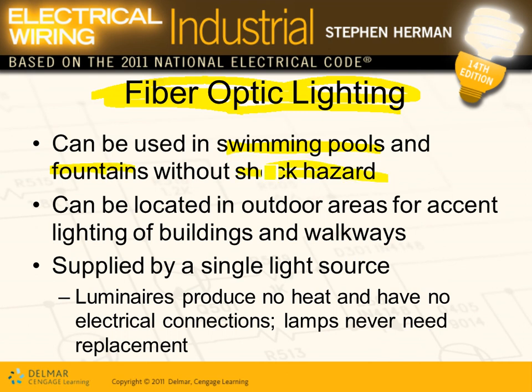So Adam, if you have wet niche luminaires inside the swimming pool or inside the fountain, instead of putting in an electrical lighting fixture that can be a shock hazard, what they do is they have a fiber optic light device. They generate the light somewhere else, and they transmit the light through a fiber optic cable into a fixture that distributes the light inside that fountain or at the bottom of the swimming pool.